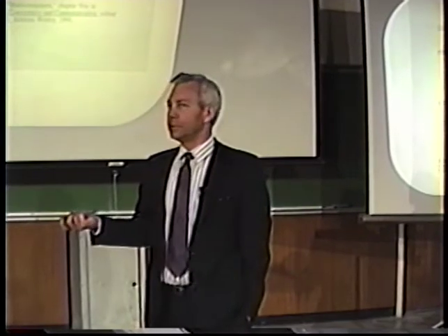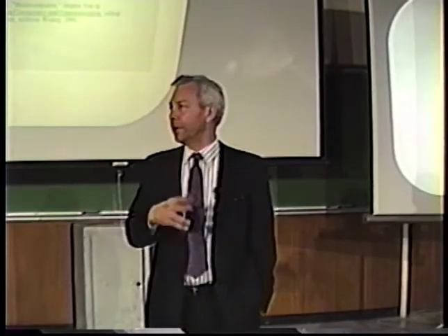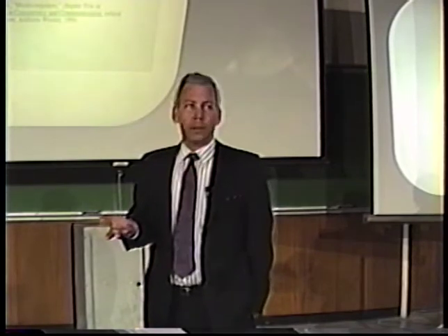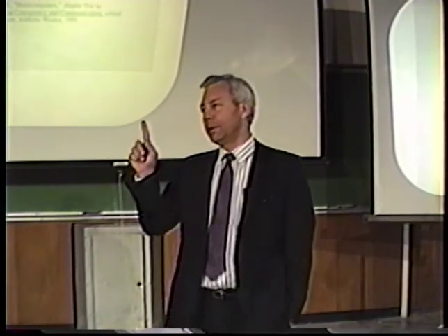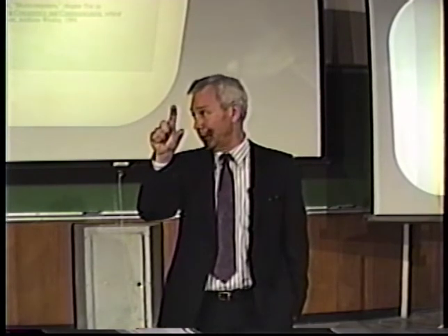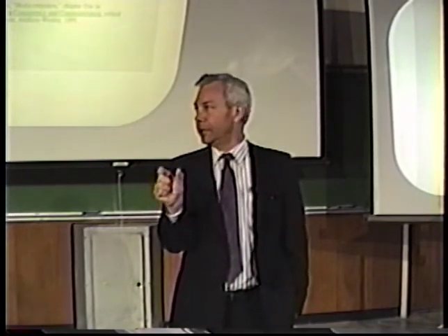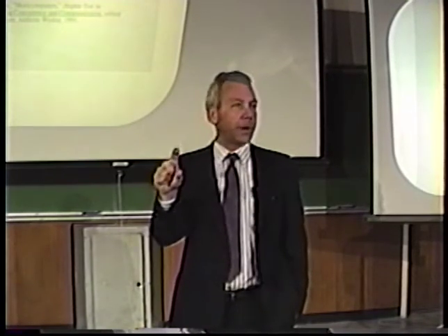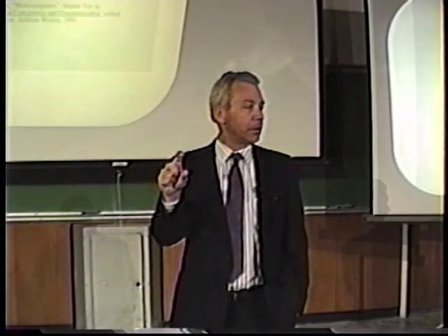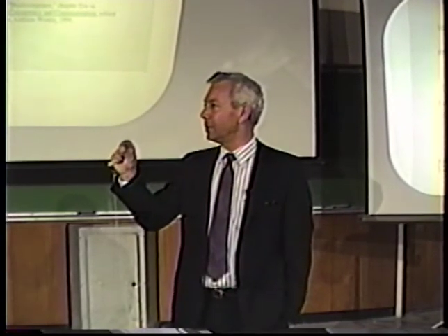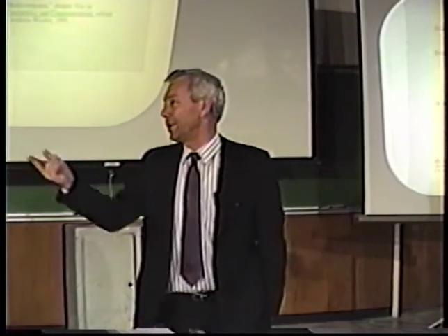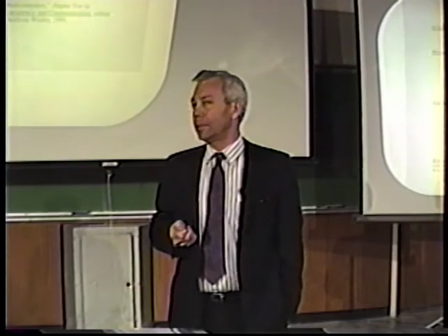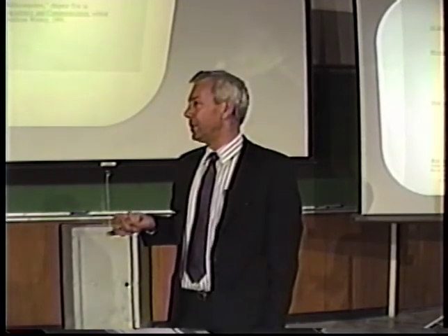for a month, or rent it for some period of time, is proportional to the area and the time. Now, if I want to use some part of a chip to do something like binary multiplication, my strong suspicion is that the cost per operation, if I can make reasonably full use of this little hunk of chip, is that it should be proportional to the area I'm using and the amount of time I'm using it. If the amount of time I'm using it is less to do this one operation, I could use it for some other hunk of time to do another such operation. So the cost per operation is sensibly the area time product.